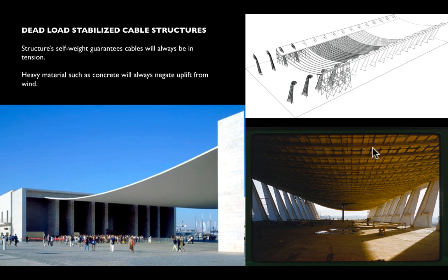And this again is a process, in this case called pre-tensioning, putting so much tension into the cables that they will never, in any foreseeable wind, experience a reversal, right? It'll never try to go into compression. And we know, of course, that cables don't do compression particularly well.